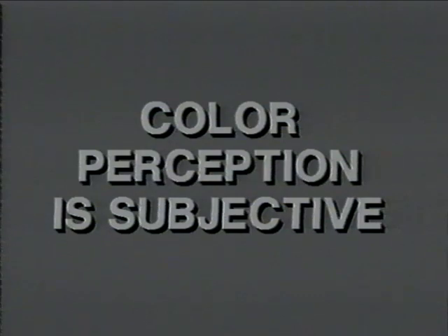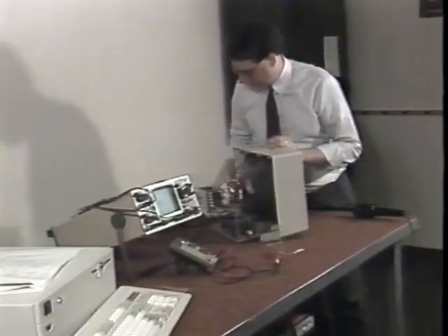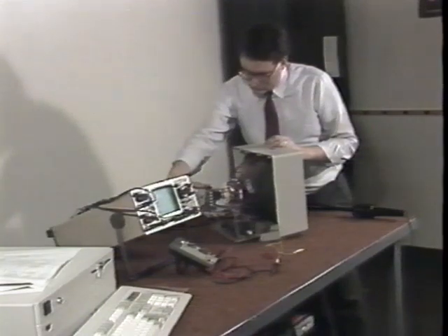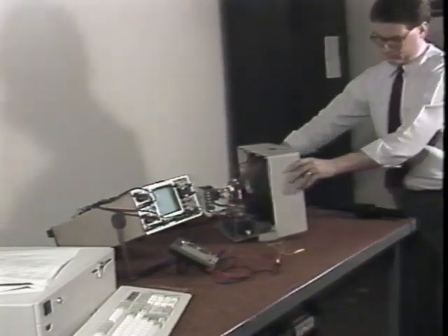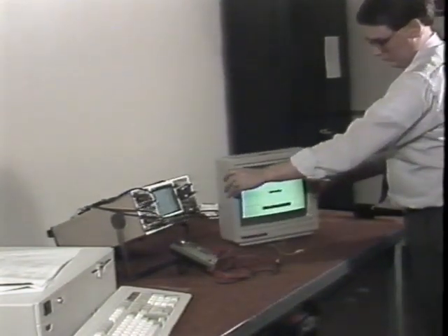To complicate matters still more, the human eye is not equally as sensitive to all colors of light. Objectively, we could make each phosphor produce exactly the same amount of light. However, the color still might not look exactly right. When we adjust the drive current, we are aligning the three output transistors so that subjectively the screen appears white when all three guns are on.